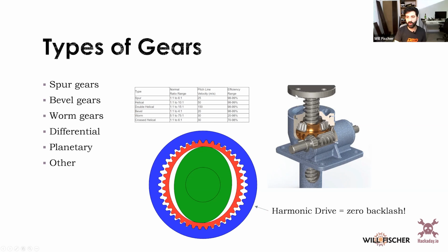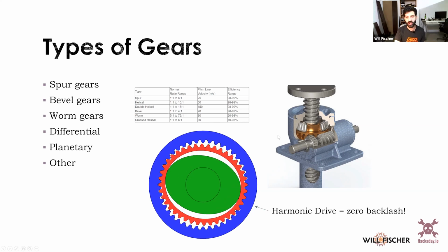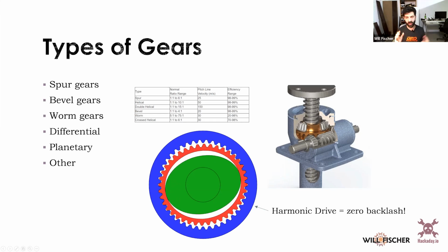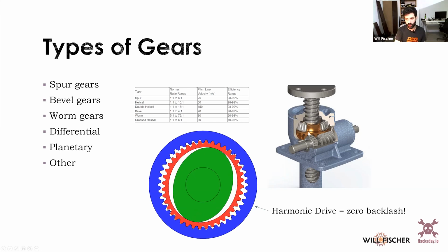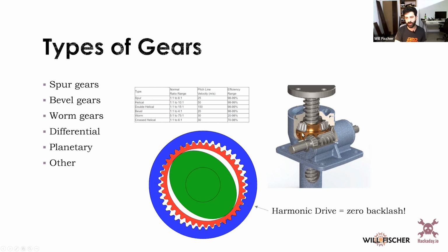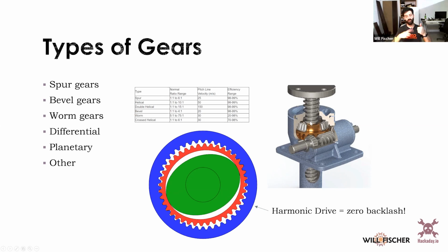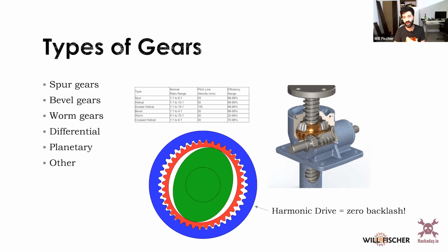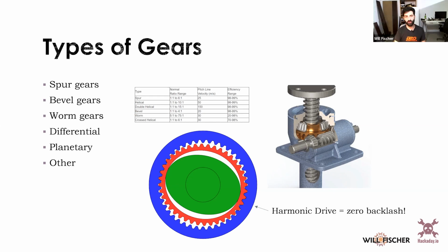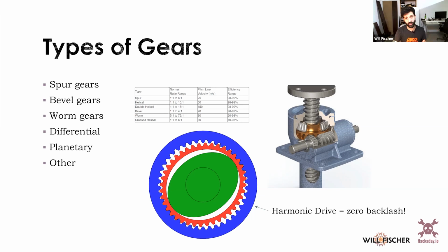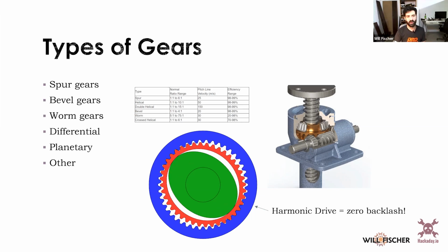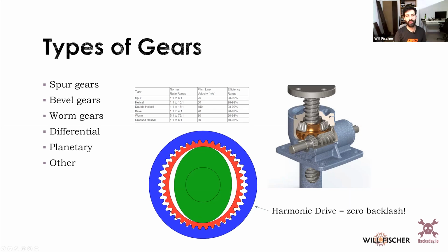The other one here that I'm showing is what's called a Joyce-Dayton jack. And this is a combination of multiple gears working together, doing interesting stuff. So it's a worm drive driving this gear here, the spur gear, that drives a threaded rod for linear movement out of a rotational thing. In an extremely compact way, they're able to produce an incredible amount of force. It's super cool. And you see these sometimes in car jacks, but also they're powered frequently to move stuff like stages around, which is really, really neat because you can put a bunch of these all over the place and you can get that kind of balance.